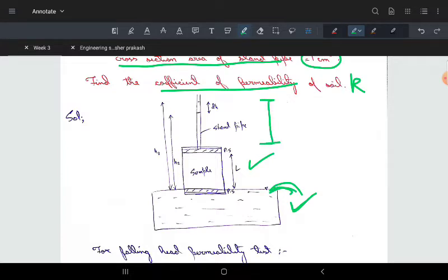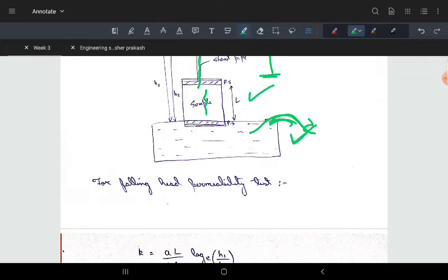We don't have a constant head here. Water is moving through the sample and moves out here, so the water level in the standpipe decreases. We have to measure how much this level decreases in how much time. That gives the permeability.